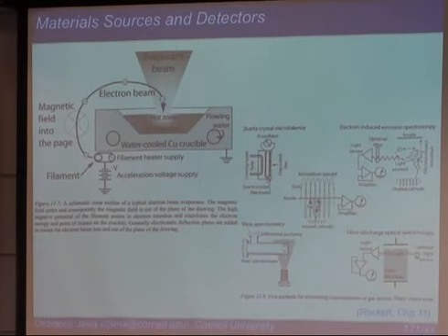Essentially, it physically imparts energy, and by the time it reaches here, you are talking about a few kilovolts of energy. So the electron is very light, by the way, right? But it's carrying an energy of a few kilovolts, so it goes and hits it, and then it melts it. You can reach the high temperature then, and this is the electron beam evaporator. This is an E-beam evaporator, right? And then you can get the flux out. Instead of getting it through melting directly, you're using an E-beam source. All right. So that's one way to get flux of atoms that are very hard to get otherwise.